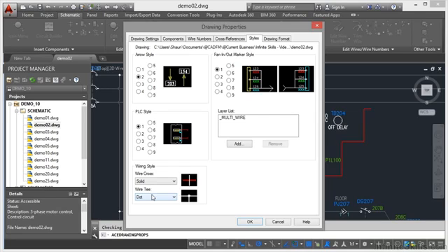Solid, I think, can also be very confusing if you print out a drawing in black and white, because those two wires are going to be two black lines on a white background. The loop always defines it nice and neatly, as far as I'm concerned. Now, also in your styles, you can see if you've got a T-junction, I use a dot, but you can also have an angle, or you can have angle 2. I prefer a dot in there.